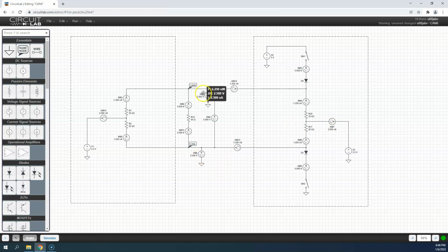So let's go ahead and get rid of the meters. I just wanted to show that these are at 2.5 volts. I used to call this the Heisenberg uncertainty principle. If you know anything about that, it basically says once you observe it, you change it. This is something test engineers kind of live by. Once I put my meter or some instrumentation in place, I've changed the circuit. So just be aware, this is some of the reason electricity sometimes doesn't make sense: the equipment that you're using is actually changing the system.